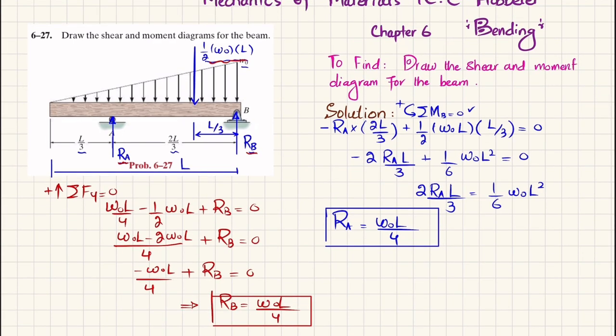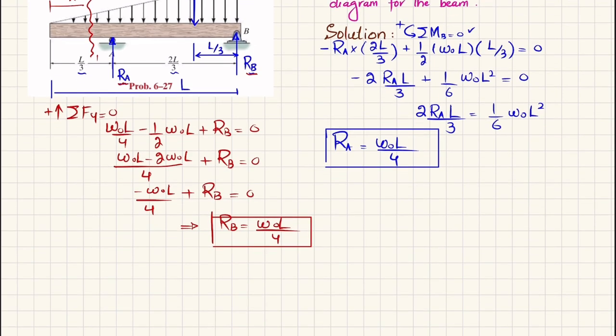The first step is that if you cut this beam over here, and let this distance be X, this is section 1, and draw the free body diagram. Let me draw it first. This is the beam, clear, and you will have a triangular load. Clear? This is the triangular load. This is the distance x where you cut this beam. When you cut it, you will have a shear force V and a moment M. This is your point 1.